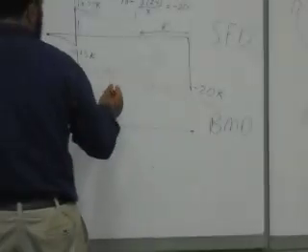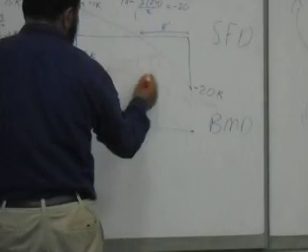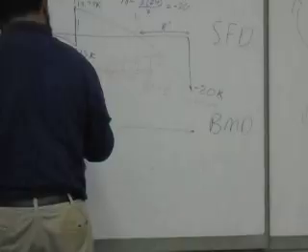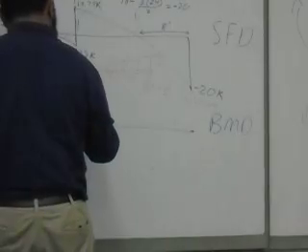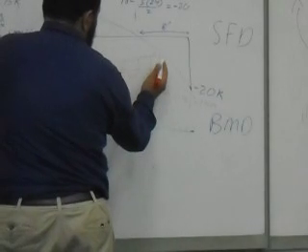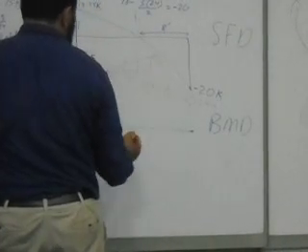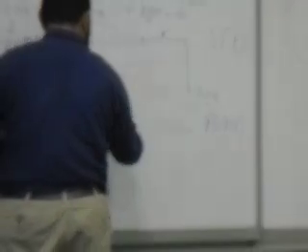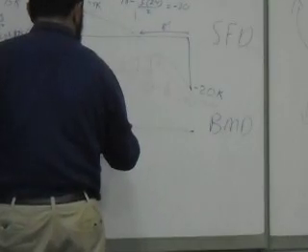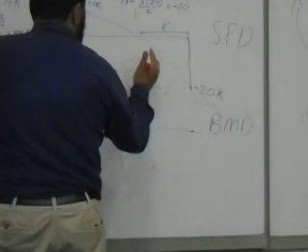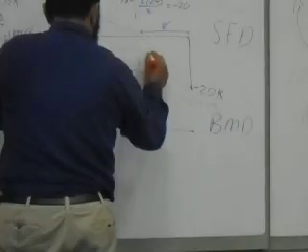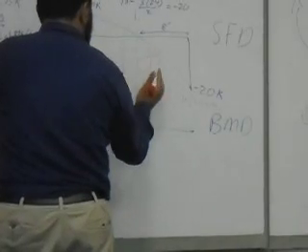So if I want to calculate the values, what I'll have here as positive moment will be what? The 16 times the 10. There it's minus. 16 times 10 is minus. So here's 16 times 10. This is positive. Minus this big distance, which is by coincidence 16. Or let's start with the load. The load times the distance 16 over 2 times the centroid of the load, which is what? The distance 16 over 3.